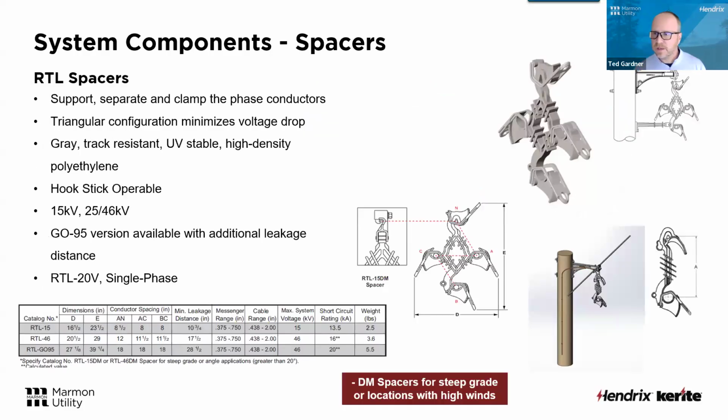The spacers themselves, like I said, are what's going to connect and isolate the phase conductors from that system neutral. And the key part of this is the material that we make it out of. One of the reasons we've maintained control and manufacturing over all these parts is so we understand that the material these spacers are made out of is identical to the material that we put on the covering of the conductor. So we know from an electrical perspective that those are going to behave and be compatible between the two.